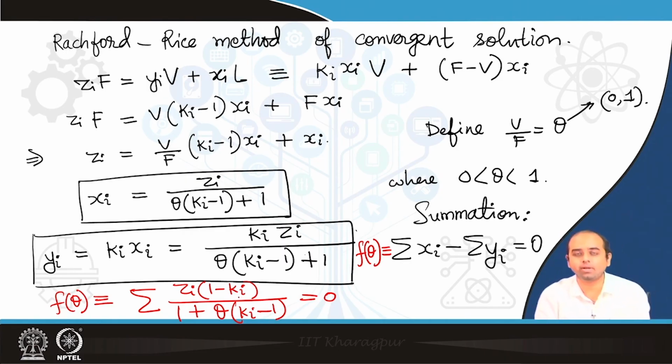You have several of these thermodynamic relations which can help you to compute these phase equilibrium constants, the vapor liquid equilibrium constants. You have those Van Laar models, UNIFAC, which can help you to calculate these constants. And typically K is a function of temperature and pressure in the system, right. So, it is not that temperature is not defined for this problem. This Ki is actually dependent on the temperature and pressure of the system that is maintained, right.